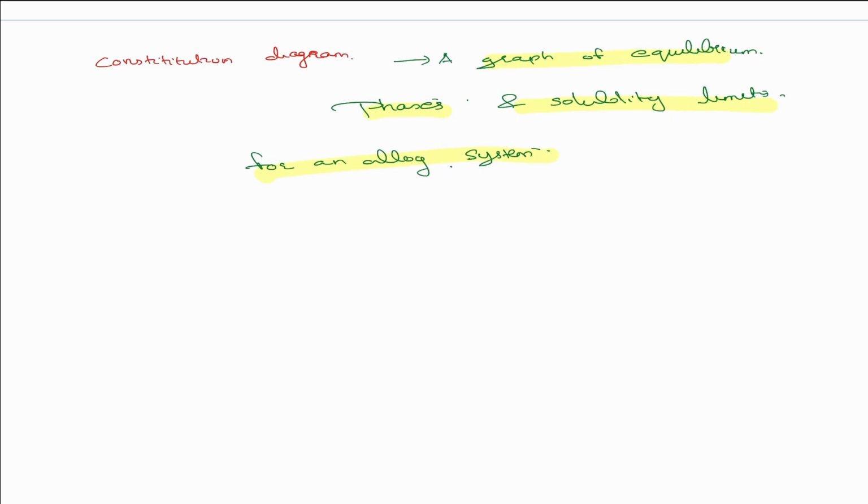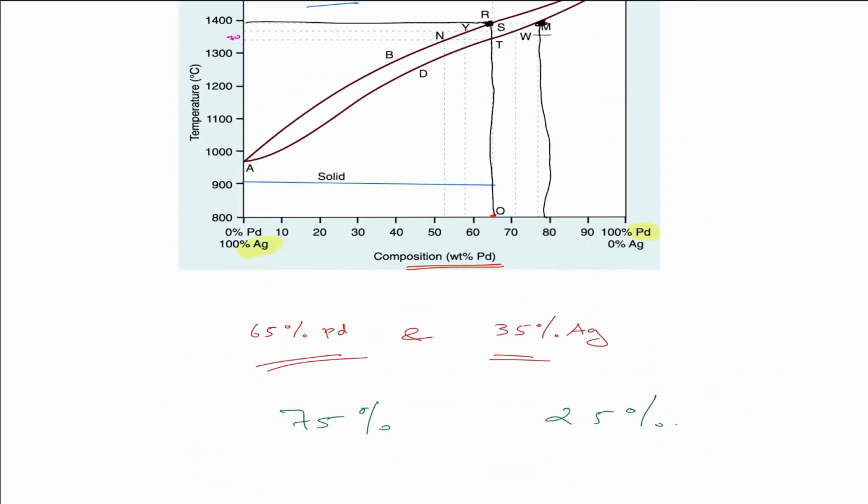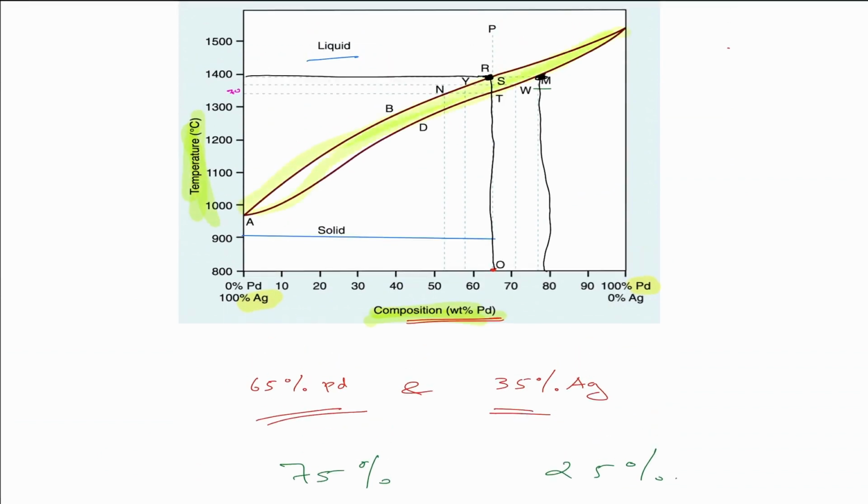Now this is where it's much more important: as a function of composition and temperature. So the important terms here are phases, solubility, composition and temperature. When it's an alloy, it is soluble at different levels. On one side it is composition, on the other side it is temperature, and there is a phase change, liquid into solid. This is what the phase diagram is.